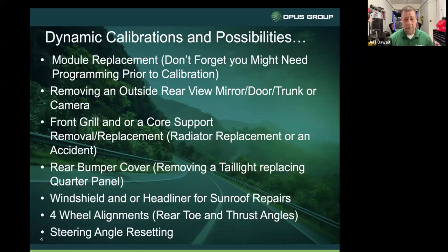So I can give you guys a very good example of this. When I was the shop foreman at Audi, I had the writers up front. They were trained to know how to look for ADAS components on vehicles, right? So we had a relatively common issue on the 4-liter twin turbos. The breather valve would go bad. To replace the breather valve, the front support of the vehicle needs to be put into a service position, and by doing so, you're loosening the core support and the headlights and everything, and it's all essentially hanging forward on the car with the bumper off of it.